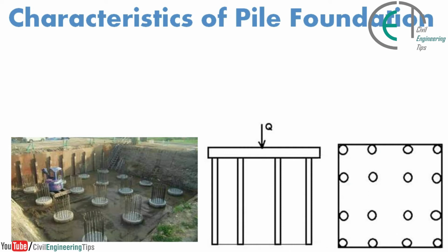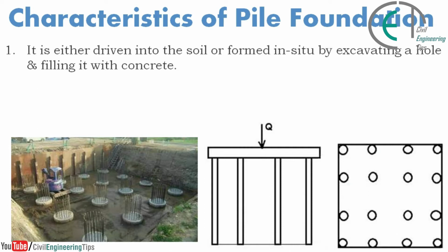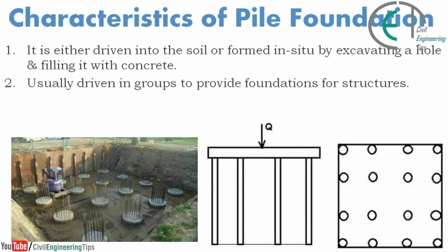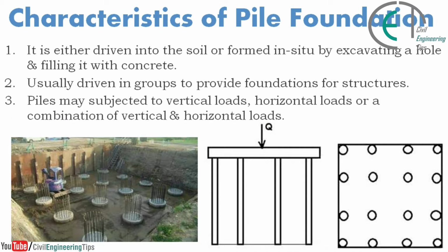Now let's have some idea about the characteristics of pile foundation. It is either driven into the soil or formed in situ by excavating a hole and filling it with concrete, usually driven in groups to provide foundations for structures. Piles may be subjected to vertical loads, horizontal loads, or a combination of vertical and horizontal loads.